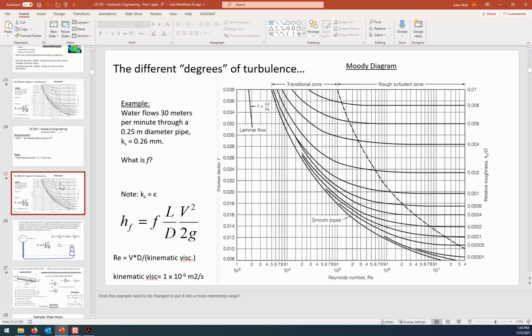All right, so the Reynolds number is basically 1.02 times 10 to the 6th. So if we look on the Moody diagram, here is our Reynolds number, 1 times 10 to the 6th, and we need to find the intersection with our F value, because what we're going to say is, what is the relative roughness that would have caused this friction factor with the Reynolds number that we have.